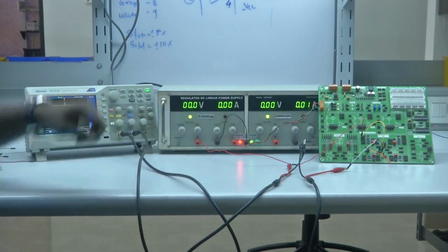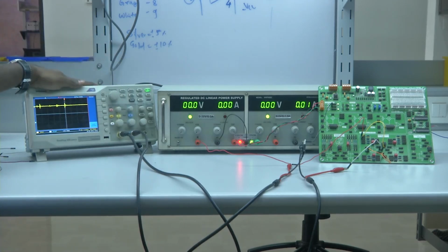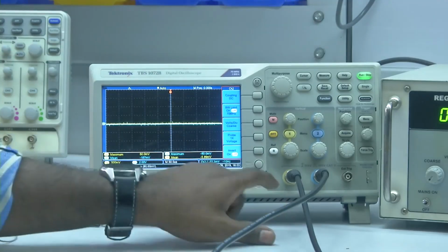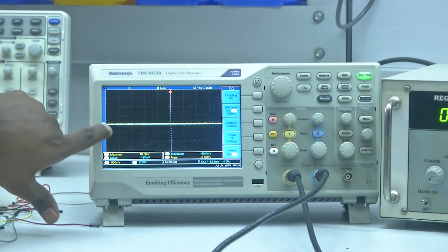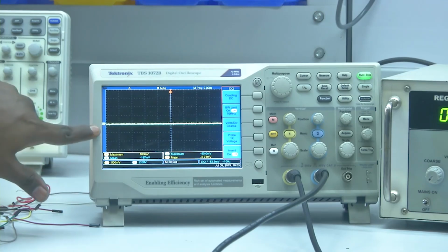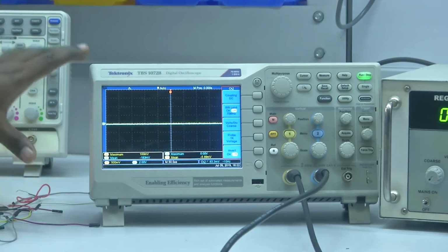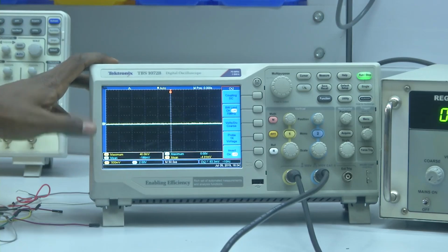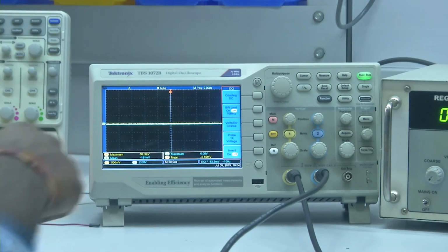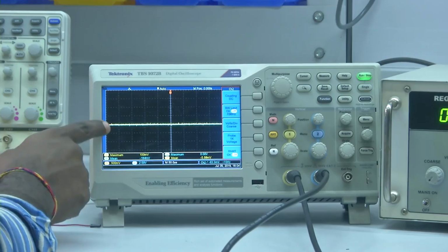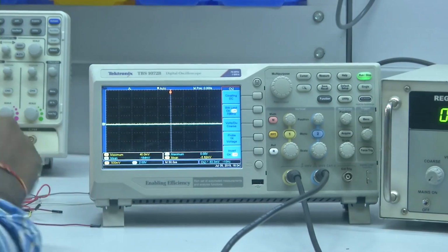Right. So, let us see by varying the input voltage what output we are getting. In this case, we have two channels. The yellow represents the input side, whatever input is being provided to the input of the resistor, and the blue indicates the output from the operational amplifier. Since the power is 0, the input voltage is 0 in this case, so the output and input are simply 0. If you observe carefully, one vertical box represents 500 millivolts, whereas for the blue one box represents 2 volts.